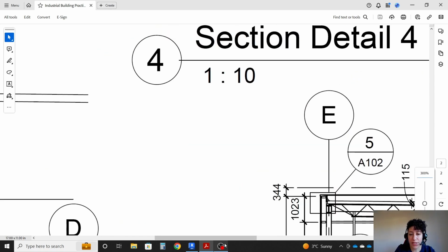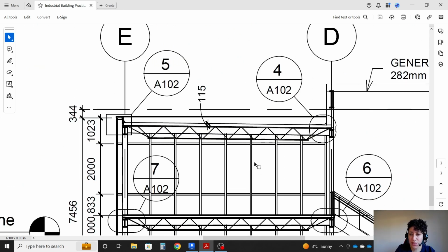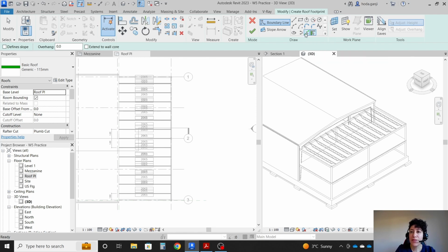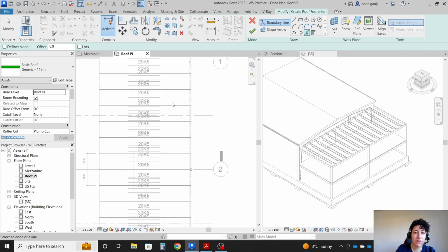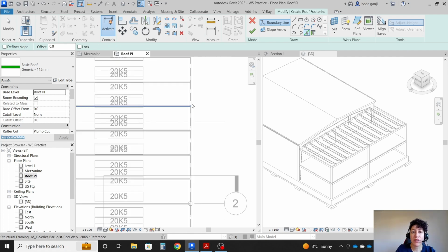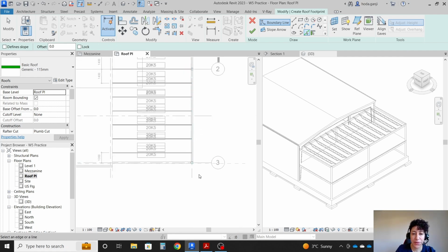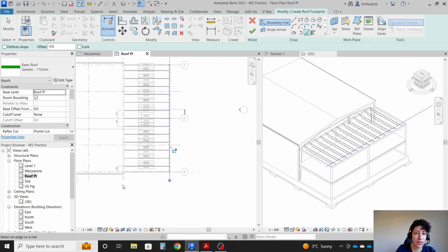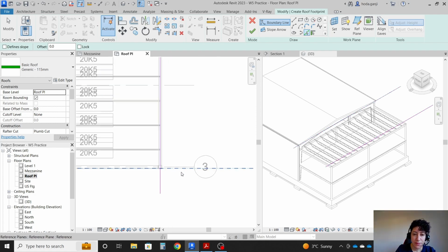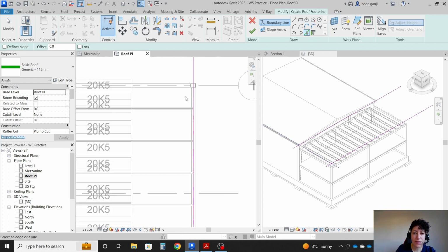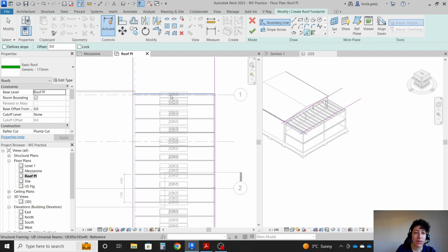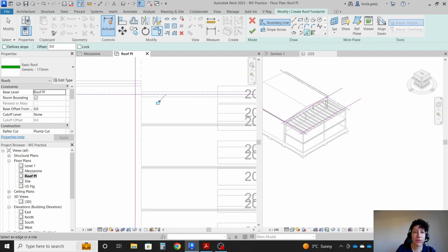I want to draw it, and later when we get to the details, if I didn't draw it correctly, we'll fix it then. We don't have the wall, so I'm gonna go with pick the lines, maybe on this view. I'll actually go with the grid lines, because the grid is exactly on the center of that beam, so then it should be good.